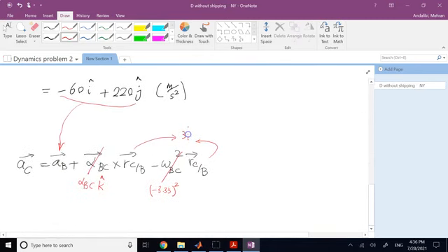So now, does this lead to anywhere? No, because I don't know this alpha BC, and I also don't know anything about A of C. From member BC, there is no information about C. And AC has two components, an X and a Y. And here there is alpha. So in general, there are three scalars unknown here. And this is a vector equality. It gives me two scalar equations, one for I, one for J. So I will be down to two equations and three unknowns, which is impossible to solve.